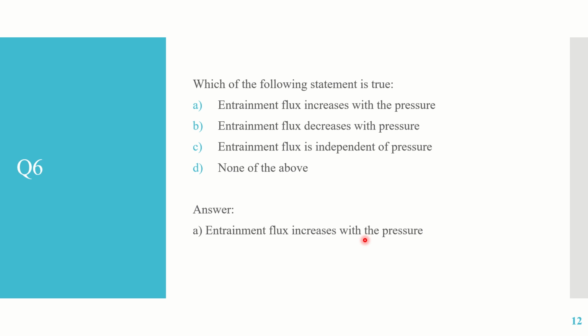So the carryover capacity increases with pressure, that is, the carrying capacity of the gas is improved with an increase in pressure. Thereby the entrainment flux also increases with an increase in pressure. So option A is the right answer. We'll go to question 7.